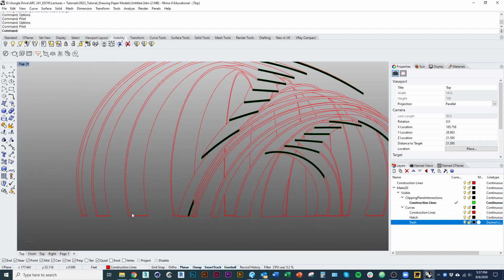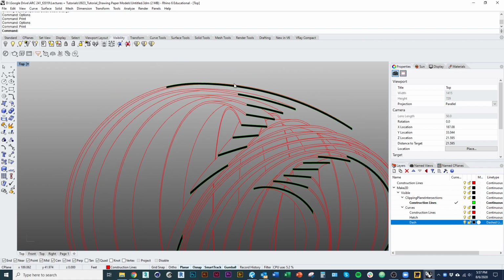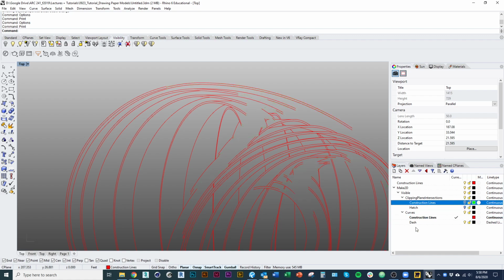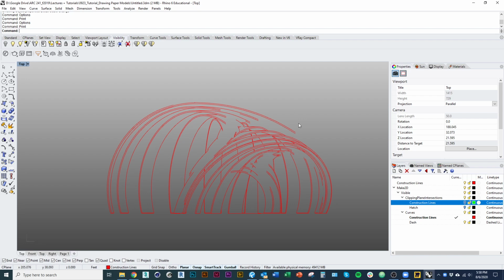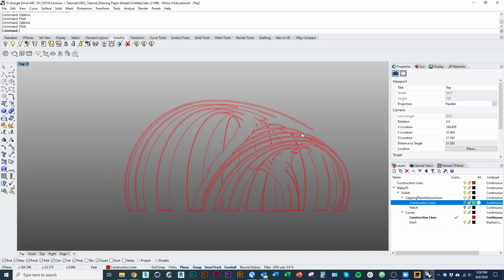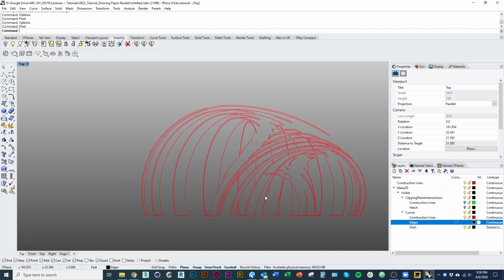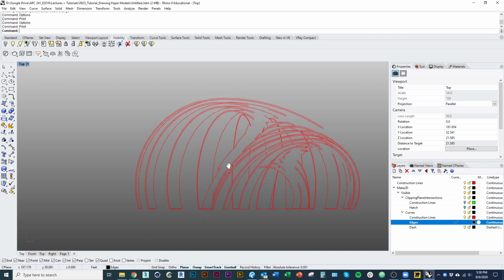So one other thing you could do is add some additional line weights to this part of the drawing. Shift this up here. I can turn that layer off. So not the poche and not the section cut. But what if I just wanted to line weight the rest of my lines to make these lines look a little bit cleaner? So I would make another layer, and I would call this my edges. In this case, what I would argue is that it's better to emphasize the silhouette of each strip to really understand where we're looking at a solid strip and where we're looking through the object.